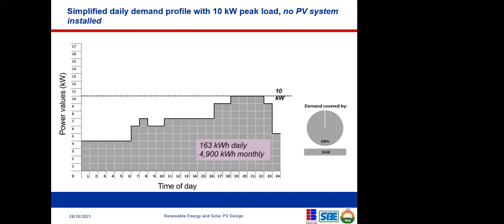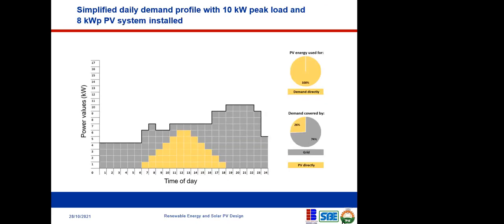So now this is a simplified demand profile. If I put that solar radiation into this, you see what I get? Now, this is why it is important that you determine the load profile of your client before you go and design your system, so that at every point in time, the energy coming from the sun is maximized. You don't over-design. If you over-design, it simply means that at some point your solar system can be redundant.